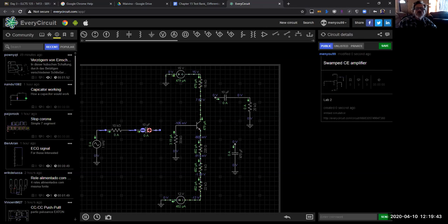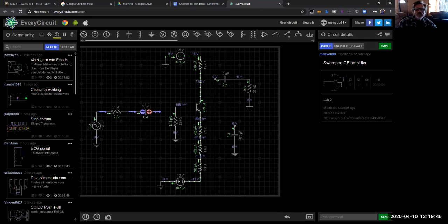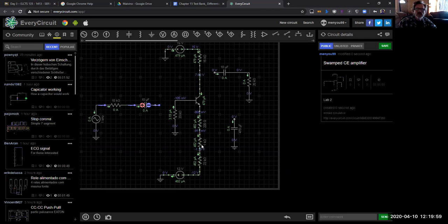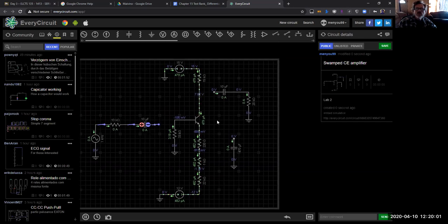By injecting the DC, notice it even lists out what the current is. I could put in a voltmeter and measure my VCE and VBE, but we're getting a smooth current flow. So in a sense, this circuit works, I am able to activate, and this amplifier would work.